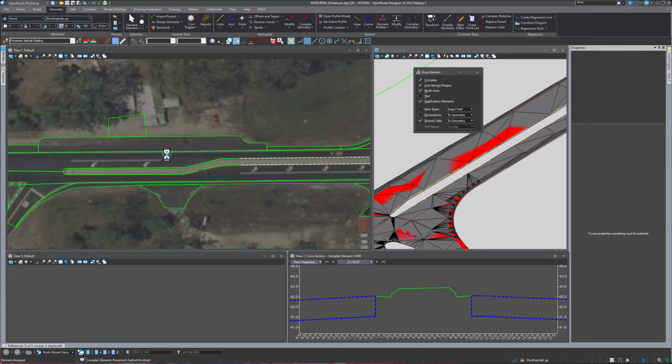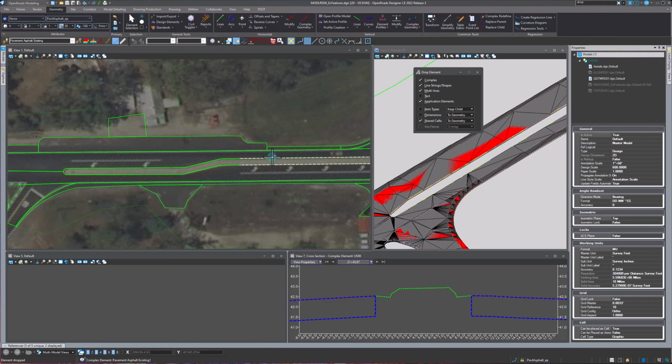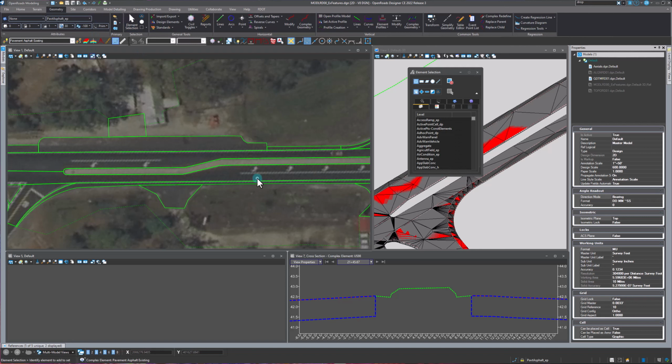So we'll drop that, and for whatever reason, it drops to the green lines here. I'm not quite sure why it's doing that. I think it's because I originally brought those in on that. What I want to do is, right now my settings have this transparency and this priority, so I'm just going to put those back to 0 for transparency and maybe make this like 200 for priority, so that the lines that I rule here end up sitting on top of everything else.